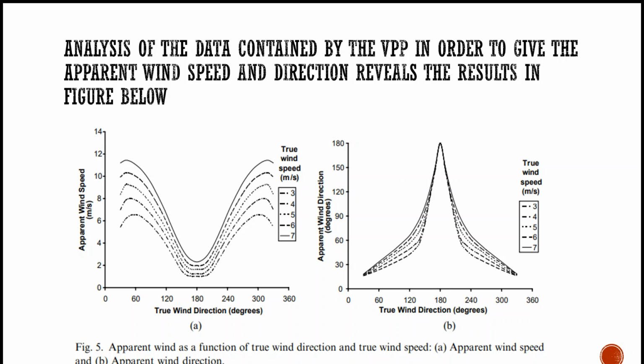If the apparent wind angle is 180 degrees, then it's a drag type force that provides the thrust. On the other hand, if the apparent wind angle is about 90 degrees, then it's a horizontal lift force that is required, and the sails need to act more like vertical wings than a drag-producing horizontal parachute.